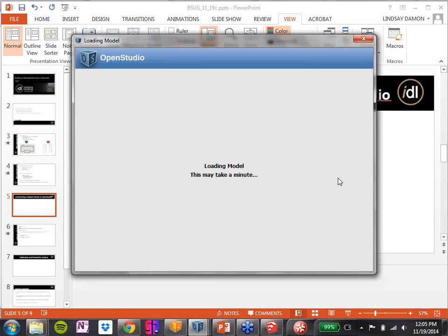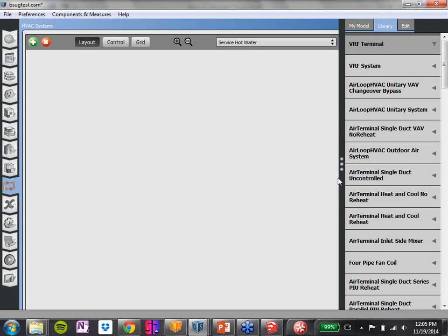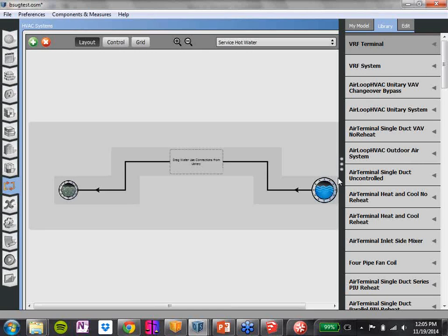I have a question real quick. Yeah. Go. Once you go into OpenStudio, I'm assuming you can't go back to SketchUp and change geometry, or can you go back and forth a little bit? It's pretty much a one-way street. So you can update in OpenStudio and see those changes happen in SketchUp, but you don't want to be updating in SketchUp and here.